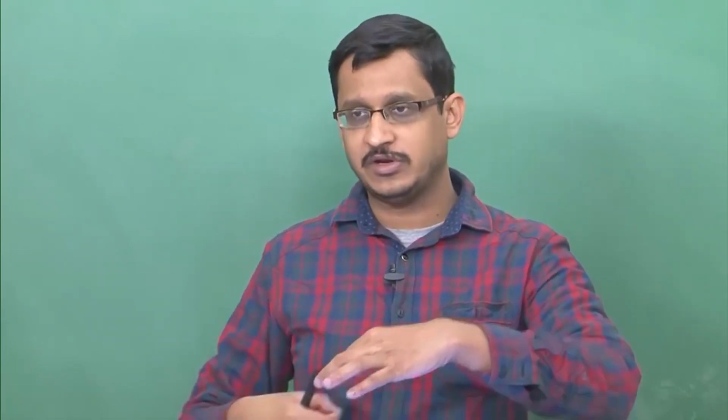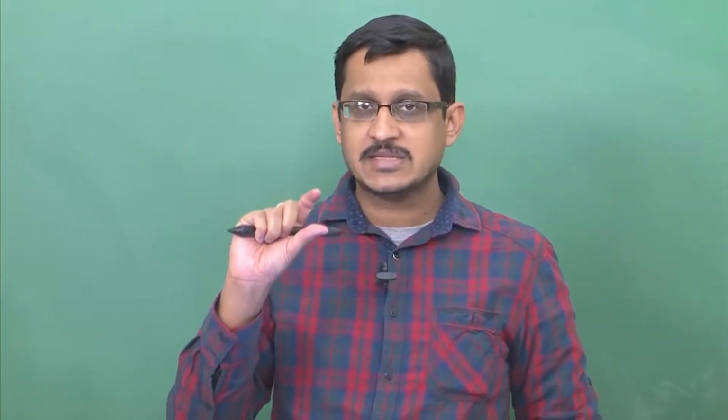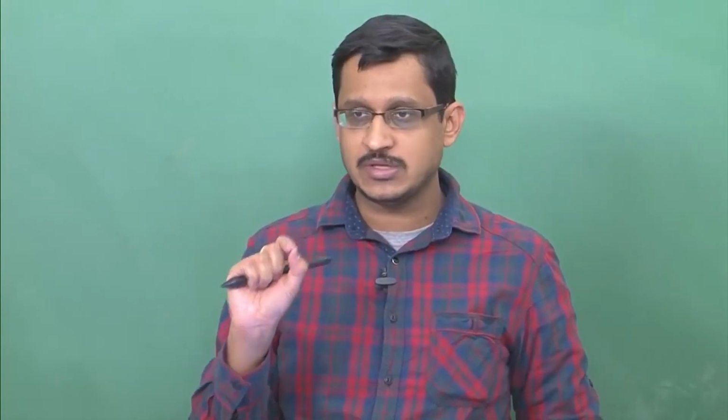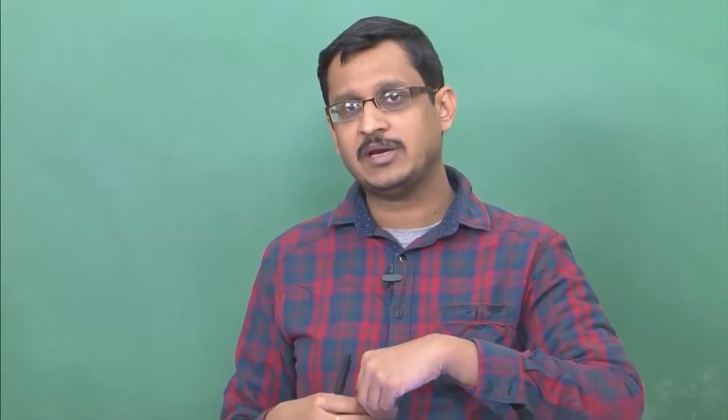Now I can actually take this piece of cross section that I have shown and move it around in the z direction, and if this coaxial cable is infinitely long, or at least very very long, then no matter where I place this surface, I am going to end up with the same amount of flux cutting through this surface, right. So if you let z go completely to infinity, then it will not really be okay, because you are now considering an infinite surface area, and the amount of magnetic flux linking to an infinite surface area will be infinity, and you will not get any meaningful results.